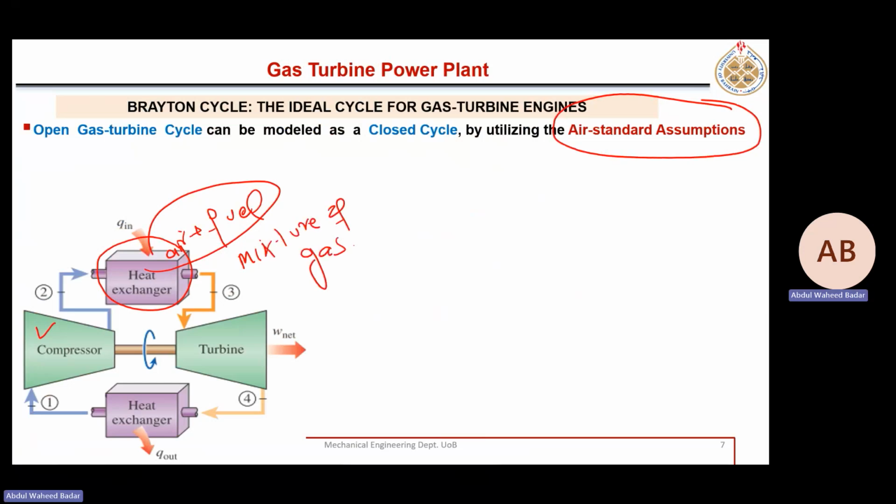But in gas power plants, normally to burn 1 kilogram of natural gas, we need around 10 to 15 kilograms of air to burn 1 kilogram of natural gas completely. But here for gas power plants, we use a much larger amount of air so that temperature remains under a reasonable value. So here we are using an air-fuel ratio of 50 or more. So for 1 kilogram of fuel, we are sending 50 kilograms or even more air.